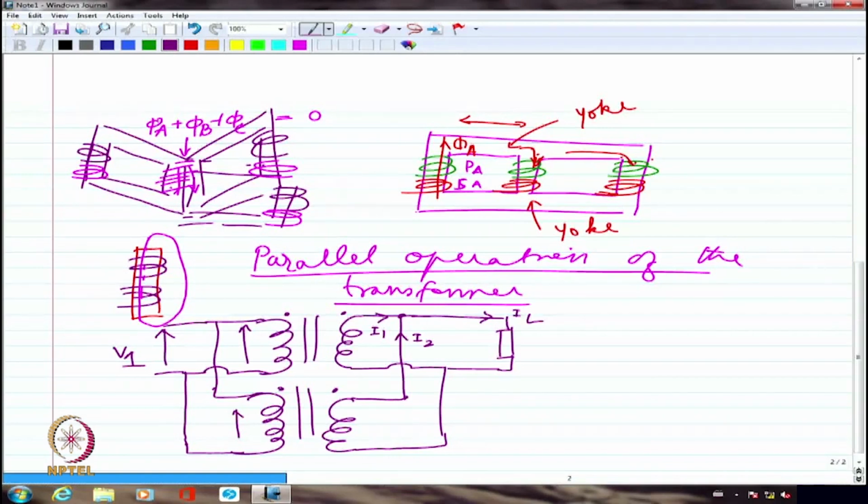One way of doing it is to remove that 100 kVA transformer completely and put in a 1 MVA transformer. Even if I put in a 1 MVA transformer, there is no guarantee that it is going to be sufficient tomorrow. So rather than that, along with this 100 kVA transformer, maybe another 200 kVA transformer was added, one more 200 kVA.